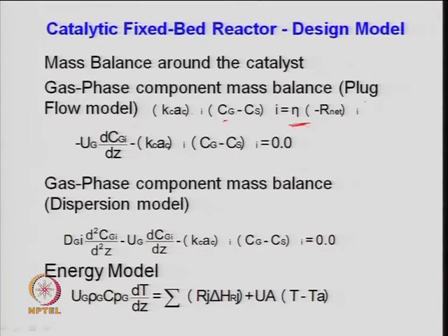So, this is just a simple gas-solid reactor, a simple packed bed reactor where you have a gas and a solid, and the gas is diffusing through that. C_g is the concentration in the gas phase minus C_s, the concentration at the surface of the solid, right. At any point, at any differential section of the reactor height, that will be the pellet effectiveness factor times the net rate. And this net rate we got from our expression; at steady state all these rates are equal. So, eta times the intrinsic rate, measured at the surface condition, right.